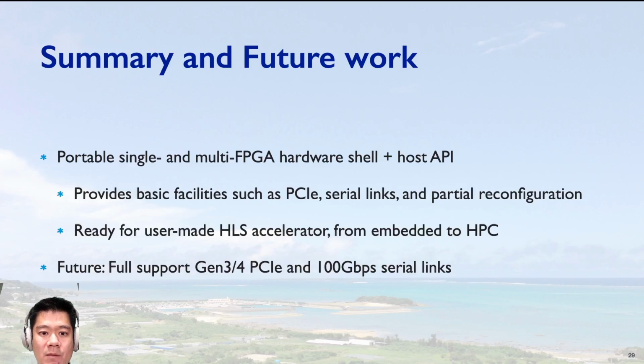So here is a summary of my presentation. OpenFC provides a portable single and multiple FPGA hardware shell with a simple host API. It provides basic facilities such as PCI Express, serial links, and partial reconfiguration features.